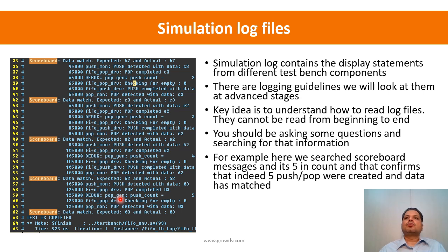And second, you should have isolated it to a few specific interfaces and a certain time duration, and see if you can root cause it using the simulation log files themselves, because generation of the waveforms takes additional time, and for complex designs the waveforms can be very big in size as well. So that is what you are expected to find out as a part of the debug process using the simulation